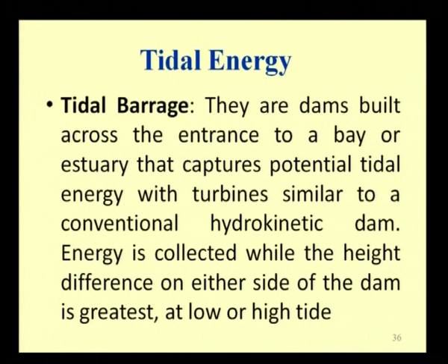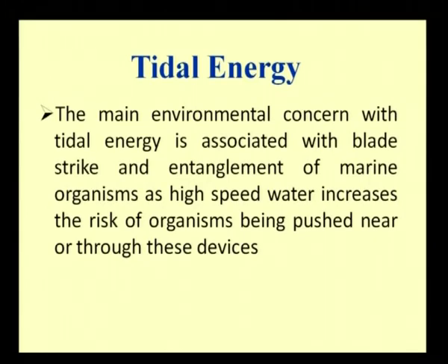And the tidal barrage, they are the dams built across the entrance to a bay or estuary that captures potential tidal energy with turbines similar to a conventional hydrokinetic dam. And the energy is collected while the height difference on either side of the dam is greatest at low or high tide. The main environmental concern with the tidal energy is associated with the blade strike and entanglement of marine organisms, as the high speed water increases the risk of organisms being pushed near or through these devices.